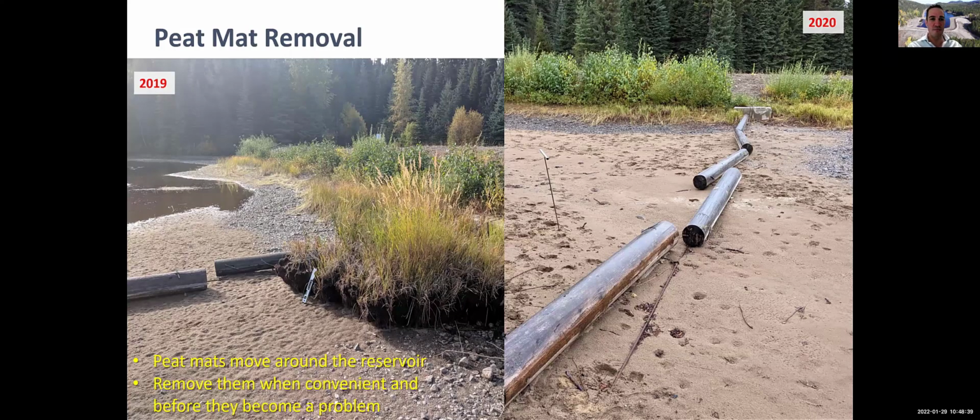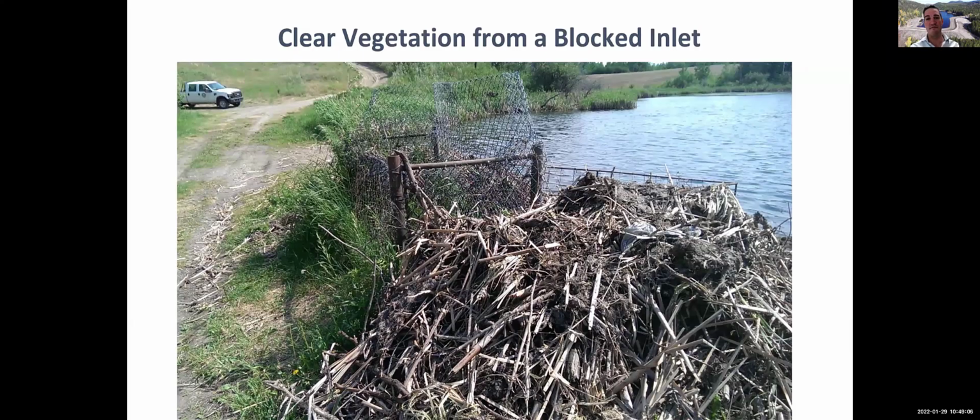So we're going to keep going. Peat mat removal. Here's a photo of a 2019 inspection, and I noted it, and well, it might have floated away, but I'm pretty sure they pulled it out. So peat mats move around the reservoir. Remove them when convenient, because they are not convenient when that water is flowing and you're in an emergency situation. You're not going to be able to move that thing or get a piece of equipment in there. So stay on top of this stuff.